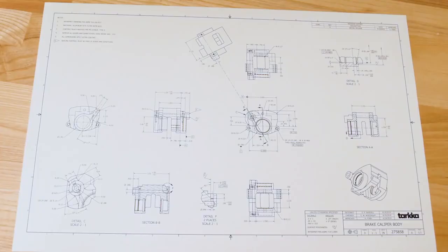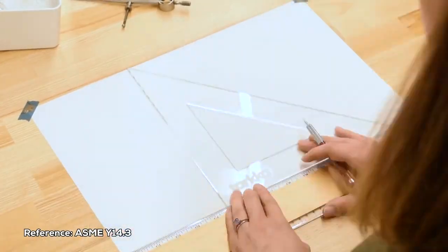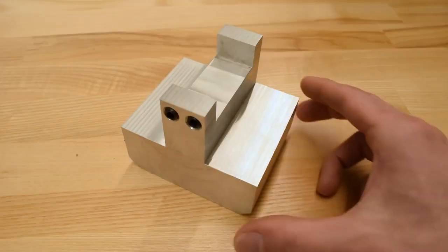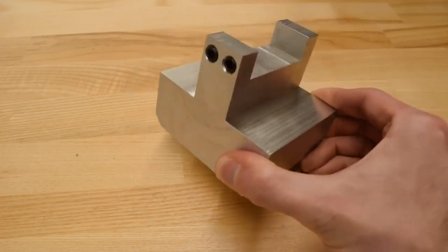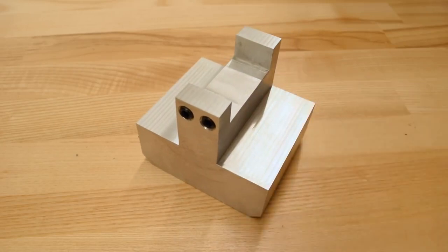The face of the drawing will usually have 2 or more views, and they must have a particular alignment to each other. We're going to switch to hand drafting for a second to talk about where this convention comes from. To draw this example part, we're going to choose a view to be our primary or front view. But there's other features of the part like the larger tapped holes in the slot that can't be seen, so we need to create additional views around the front view that show them.